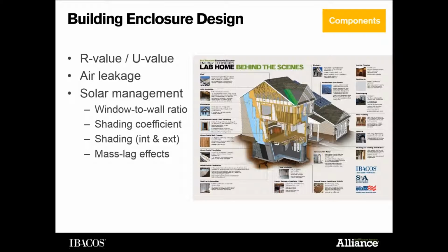And then these other factors. Solar management, I think, is a key that we need to start looking at with home builders when designing elevations. How many windows do you place that are facing south? And then from the inside of those rooms where you have a lot of window, what is the floor area of those rooms? Because when you have more window area versus floor area, we get into some issues with overheating or overcooling.